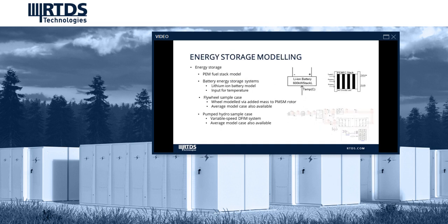The RSCAD component library has several options for energy storage modeling. We have a PEM-type fuel cell component with inputs of cell temperature and anode-cathode pressure. We have a lithium-ion battery model that will be used today, and the focus of this model is the electrical behavior of the battery. It's not a chemical model.